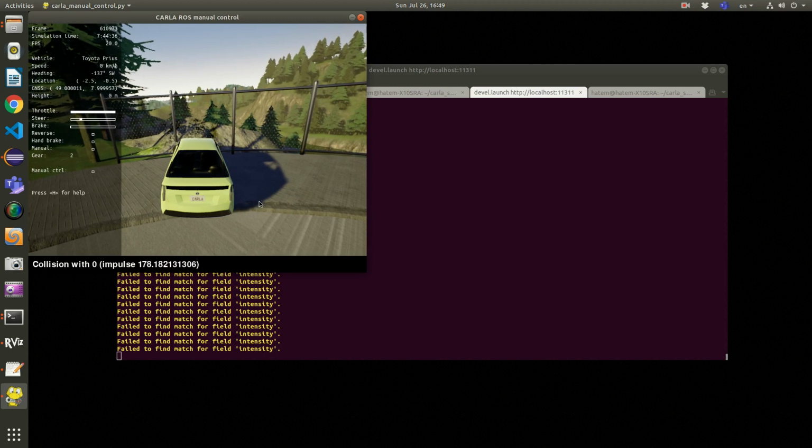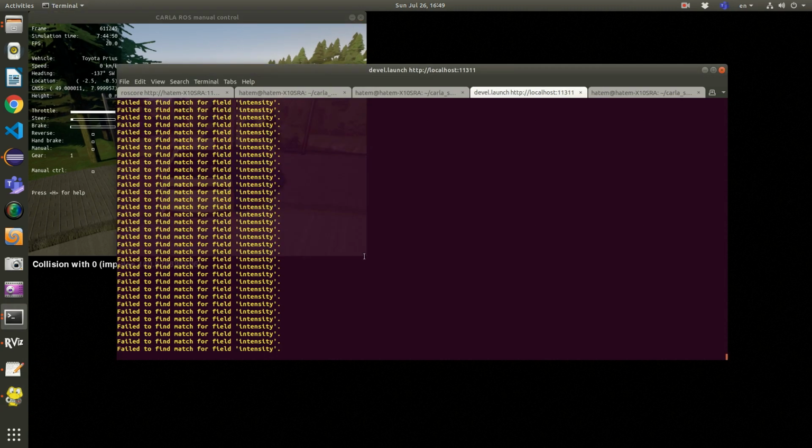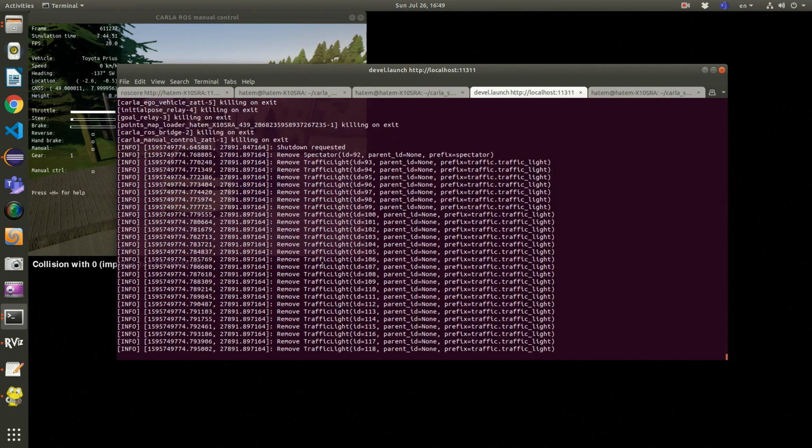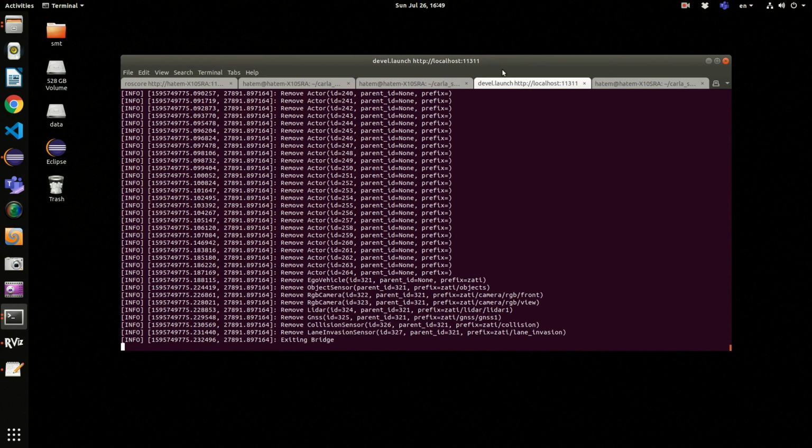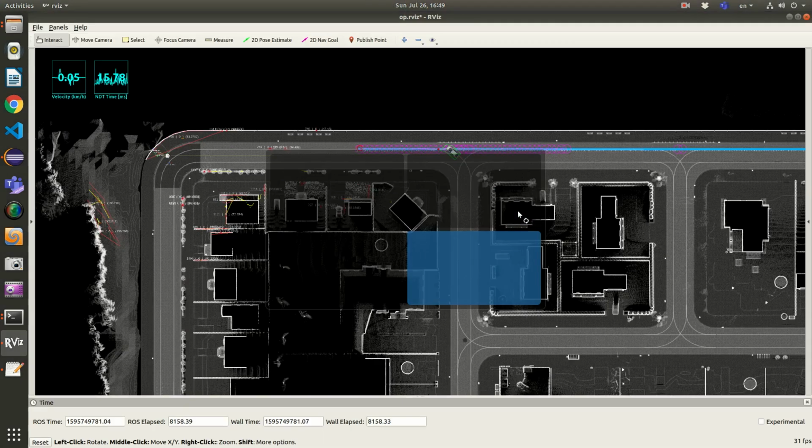This can be solved in another module in the Autoware stack. The monitor can detect that and block, send 0, or send a more reasonable velocity to the controller. So this is not a big problem. If we have continuous localization, then this will work fine, as in examples 1 and 2.